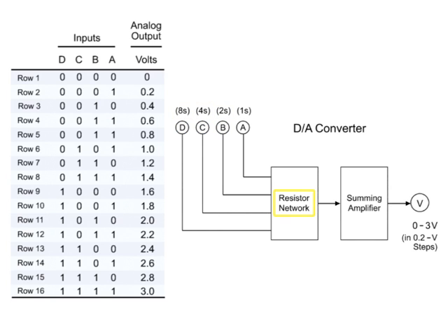The resistor network will account for these input differences by using a specific arrangement of resistors to modify the digital signal. The summing amplifier receives the output voltage from the resistor network and amplifies it to the expected voltages.